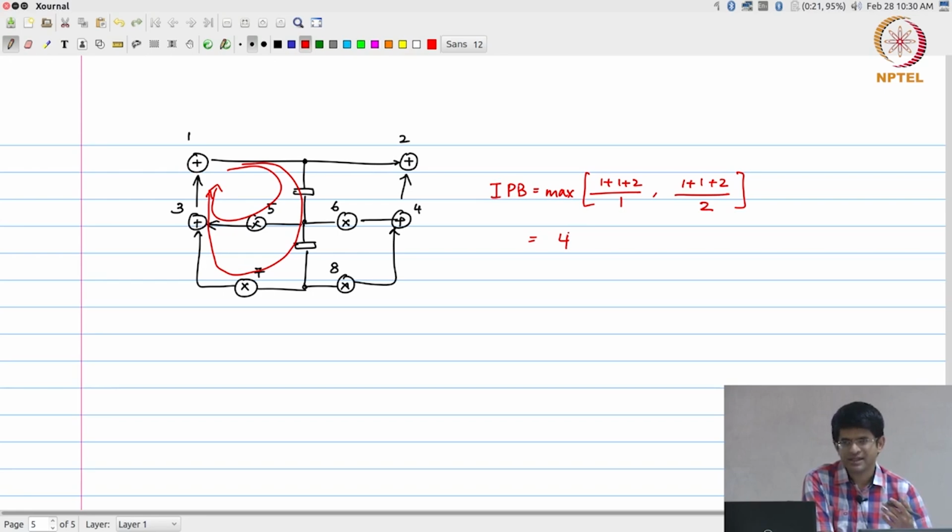The reason why I say it separately is that pipelining is sometimes easier to visualize, easier to see where I can do it. For example, I can fairly easily see that this is a potential cut set for pipelining, and if I pipeline along that cut set, that straight away achieves my objective, which is that my critical path has reduced to 4. So let's see how that helps us.